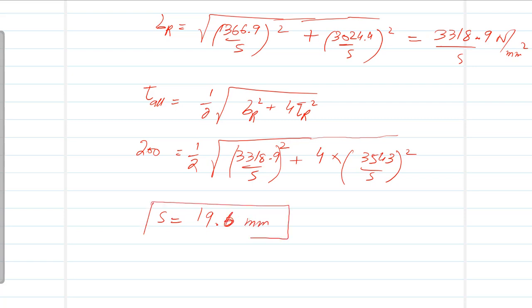So see, this problem is complicated because of two reasons. First, you have the asymmetric weld. That is the most difficult case. If you have a symmetric weld, definitely on both these edges the stress will be the same. But in case of non-symmetric welds in both planes, like an L-shaped weld, the problem becomes difficult, and that's why you need to find the stresses at both these points.